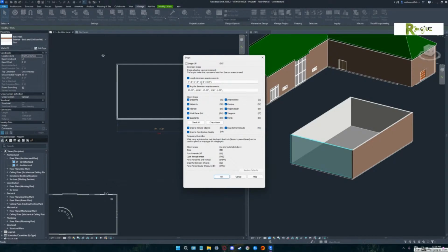So it's every 4 feet, every 6 inches. Well, that 6 inches is a bad idea when you're drawing in masonry, because what we actually draw when we're drawing with brick is going to be every 4 inches. So in other words, a brick is 8 inches long. A block is 16 inches long.